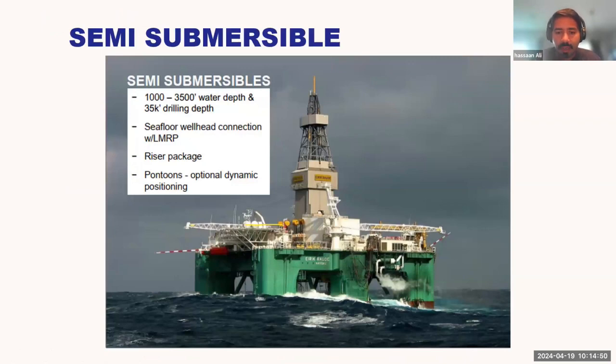Semi-submersibles do not have legs resting on the seafloor. They have pontoons, effectively, which are dynamically positioned so that the pontoons have a water level. As you have to stabilize your rig, you will increase or decrease the water level on those pontoons. And you will have thrusters around the rig that will dynamically position it so that it doesn't move, and it can actually drill quite deep.